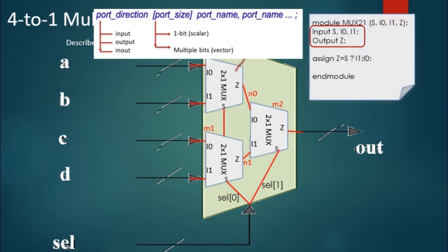before I further explain how to connect the 3 units of the multiplexers, let me do a quick revision on the coding for the multiplexer 2:1. So first, when you want to describe a module, say for example here multiplexer 2:1, first you need to declare the input and output ports. So you declare using this format where you start with the keyword input or output depending on the type of the ports you want to declare here.